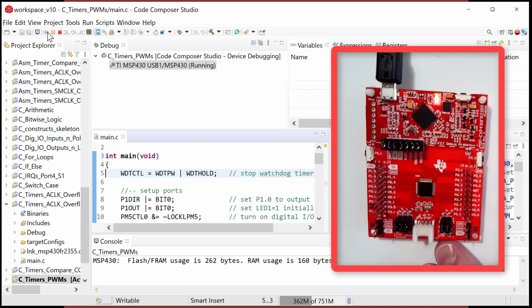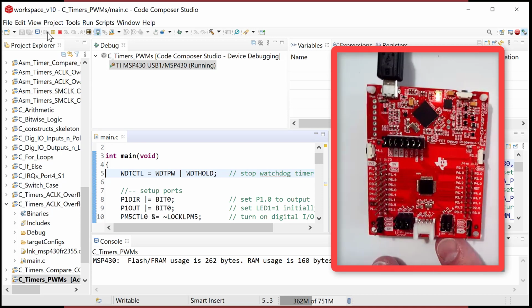So we did it. Let's try to look at the period. 1001, 1002, 1003, 1004, 1005. This is awesome. It's proving to me that we have a pulse width modulated signal. I know we're not looking at it with an oscilloscope, but you can see it's a tiny flash and then it repeats every second. It's kind of interesting that that's 50 milliseconds. That's not really a lot. Whether or not the light coming out is exactly 50 milliseconds, it might be that the LED charges up and then discharges, so it might be a longer flash than 50 milliseconds, but it's absolutely being driven with a signal that's 50 milliseconds.